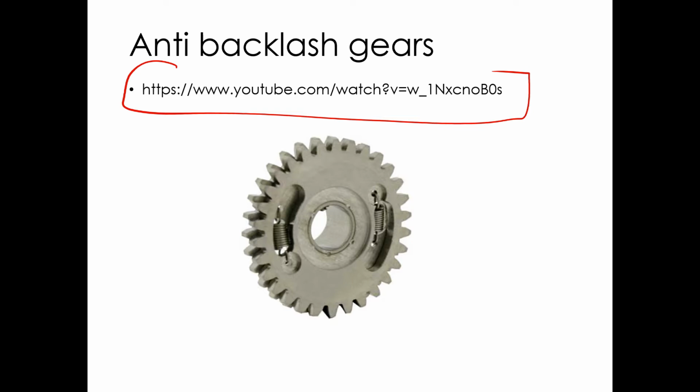It shows different anti-backlash gears. You see gears like this that have springs in them. These are smoother, but they don't eliminate backlash. What happens is you have a gear that's going to ride on one tooth of the mating gear, and this one is going to ride on another tooth. And so there's no backlash, but what's holding these things apart is the spring tension in here.